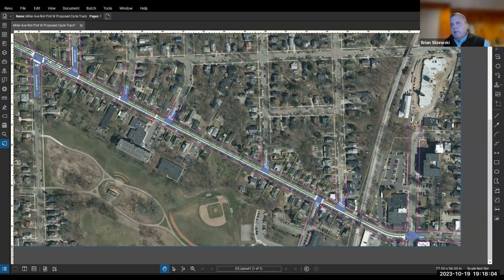The curbs do not get replaced. That's certainly a huge cost issue with just the curb, but that also impacts the potential stormwater costs. So by being able to maintain the existing curbs and replace the asphalt road between the 2 curbs, that's what we call a rehabilitation project. So that's really where that term comes from on this project. Okay.